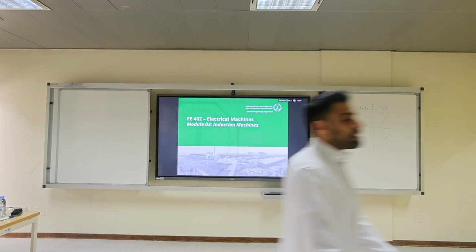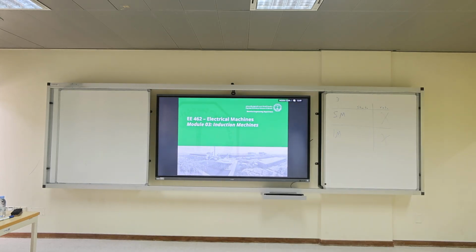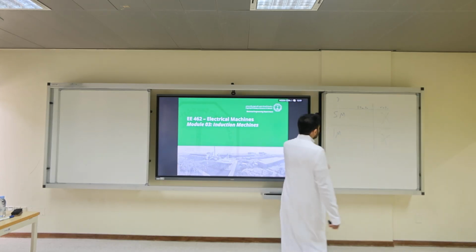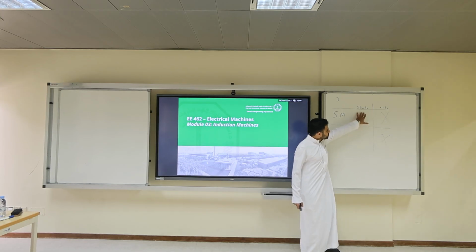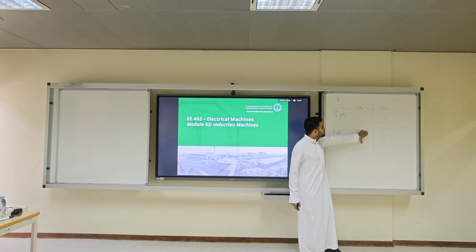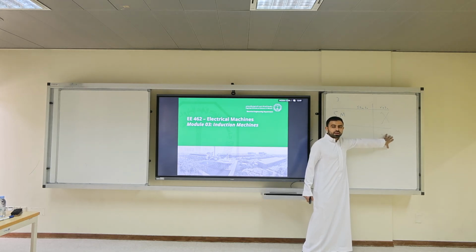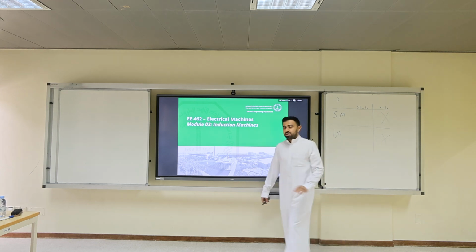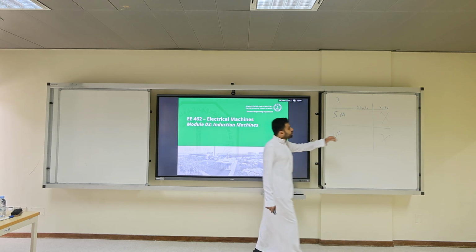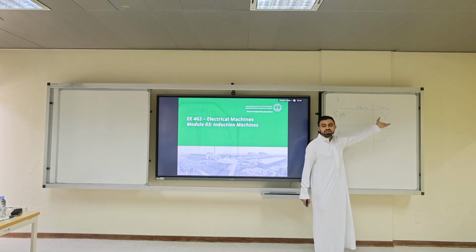Okay, so that's the thing about it. For the rotating MMF, what will happen? It will induce voltage on a rotor. And this induced voltage will have a current of frequency FR, which is S times F. However, the rotor of the synchronous machine has DC.